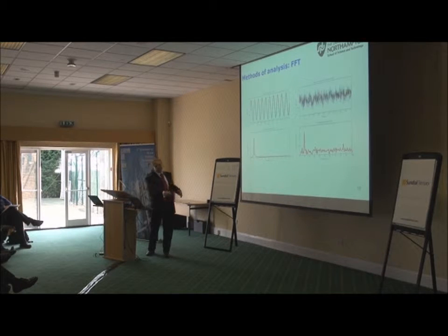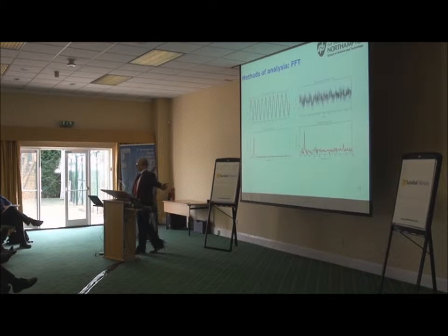In this example, I took this sine wave and included some noise, and from this background noise, the 10 Hertz is still present. Very often you would see this type of signal when you put your PMT or an accelerometer in the lift car. And you have to do FFT, which most of us know.